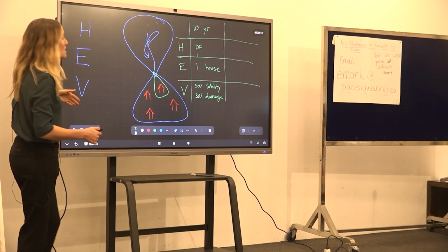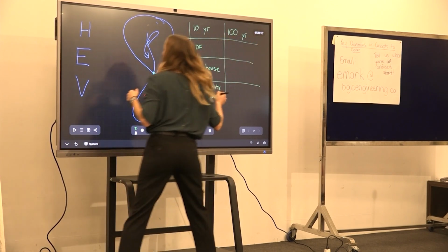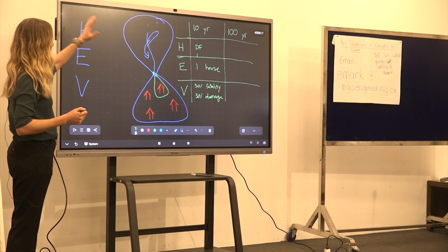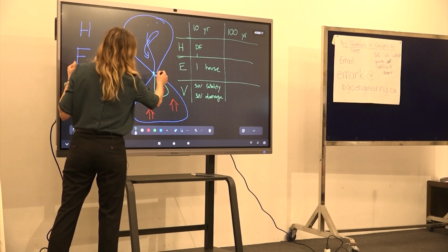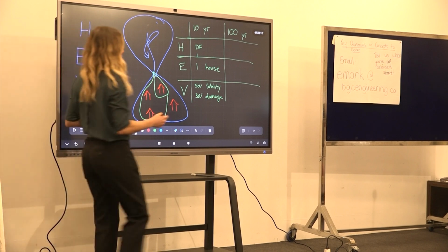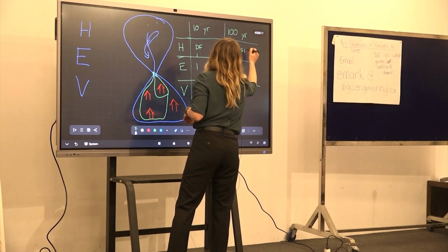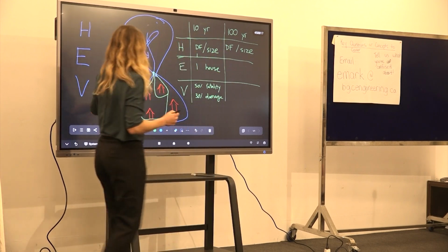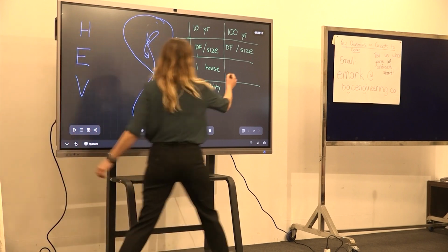So if we were to work through the same process for a 100-year debris flow, let's say that I do my analysis, I figure out how big that 100-year event is, I do a runout model, and the 100-year event goes this far. So it's a debris flow, but then it has a certain size and frequency. What would be the exposure for this event? 3 houses. Yeah.